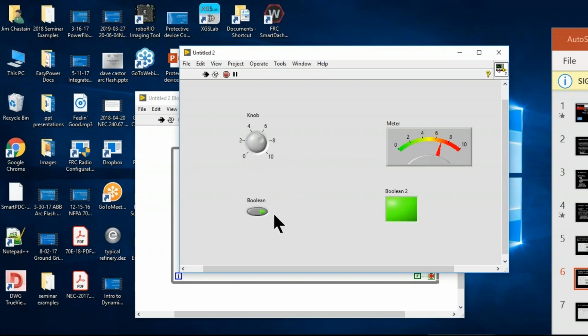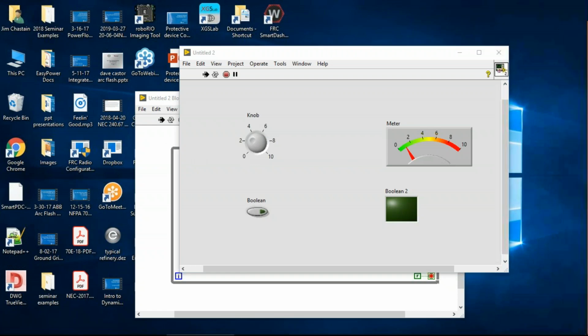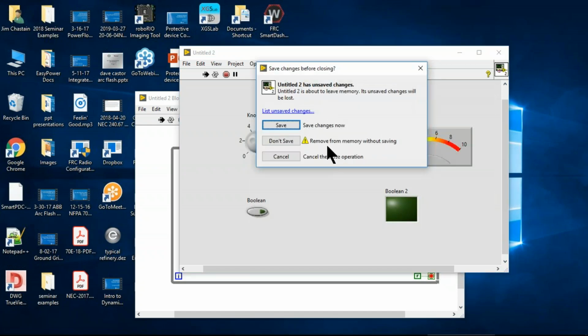This could be a safety switch. This could be a limit switch that says we are aiming the wrong direction. It could be something else that says we're too close, but basically it's a go, no-go signal, and we're gating the analog output. Very useful function, and it's used all the time in robotic control systems.